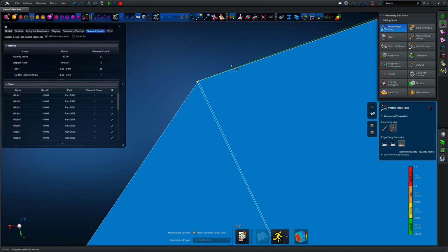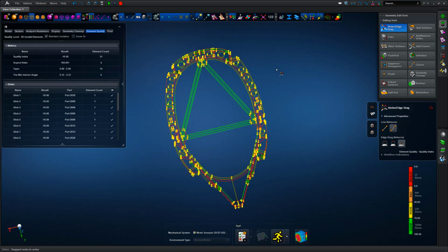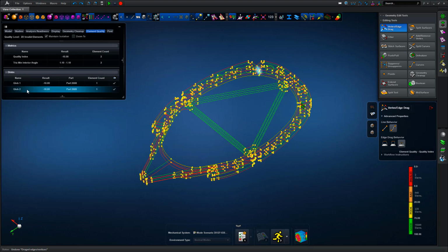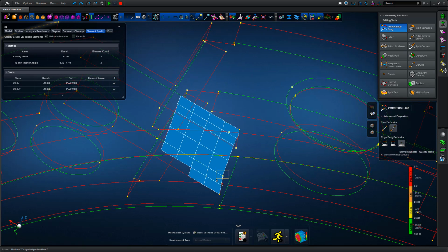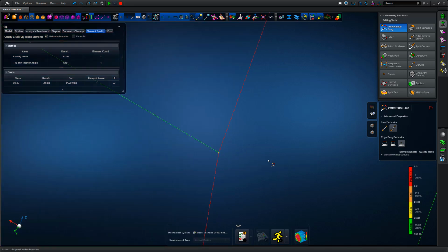I'm going to skip a couple of steps in a moment, but I'm giving you an indication of how you work on the subassembly and a full assembly definition in terms of element quality. Jumping a couple of steps and tidying up the remaining poor quality regions, these are all just slight extensions of the mid-surfacing operation.